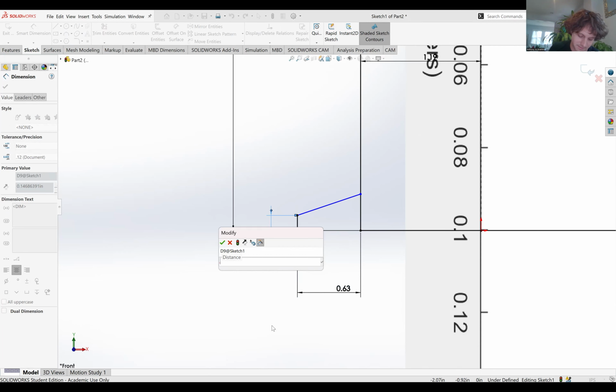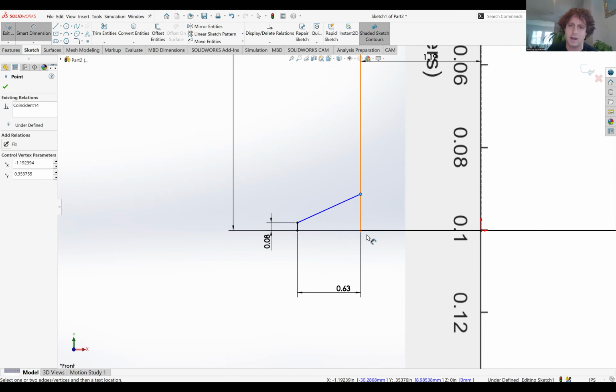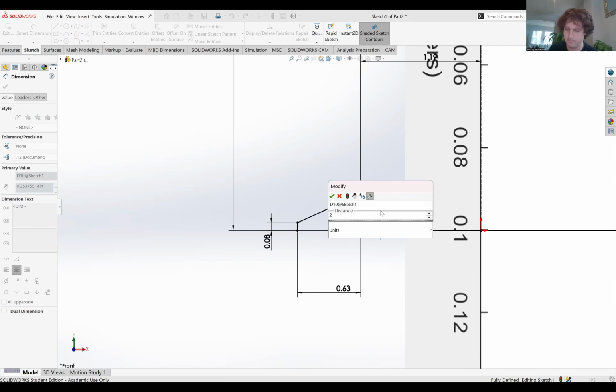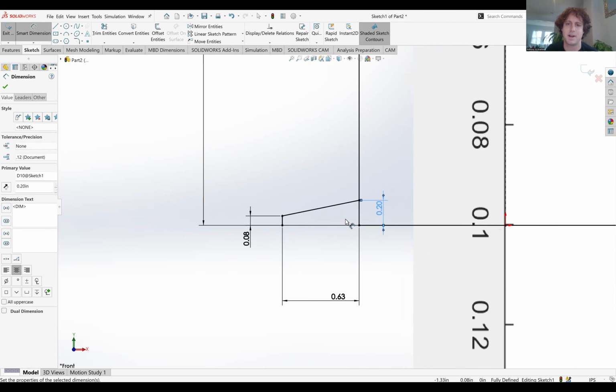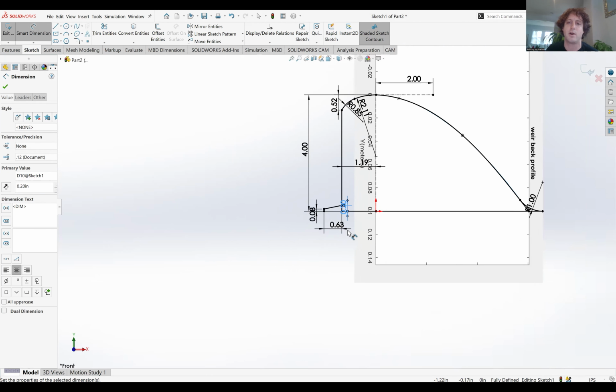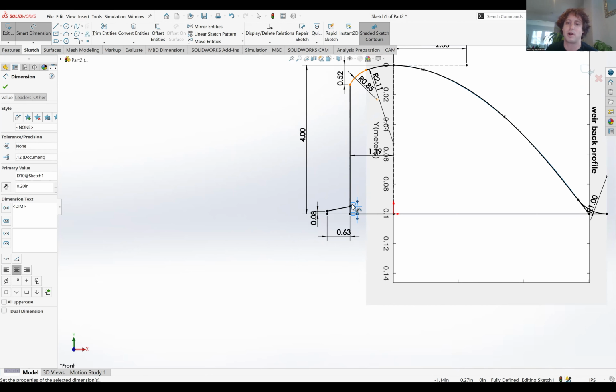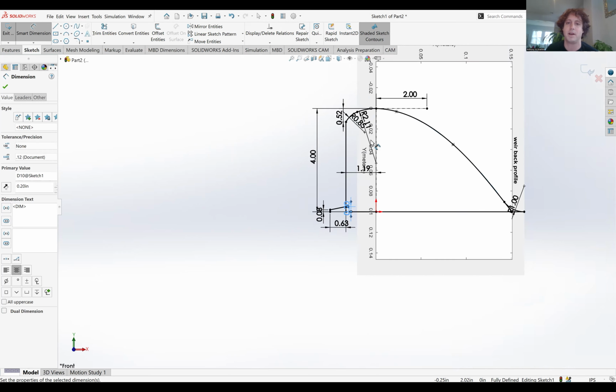I'm going to go with 0.075. You could do 0.1 as well. And then I'm going to make this very small here, to be 0.2. I'm not going to simulate this, but I'm trying to make it really small so that hopefully it doesn't really affect what we've done over here. It probably does, so you need to write about that in your lab report. If you do want to, you could try the method where it submerges your nut a little bit farther. You just have to back your hole up this distance, 0.625 of an inch.